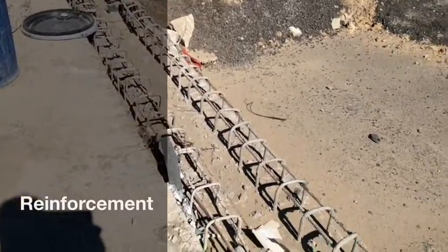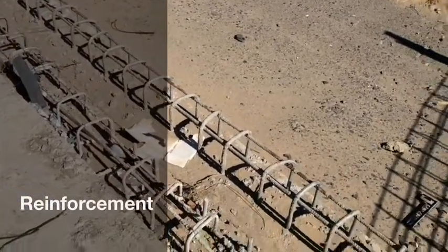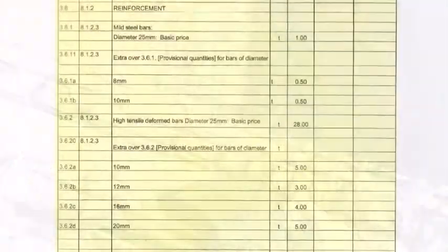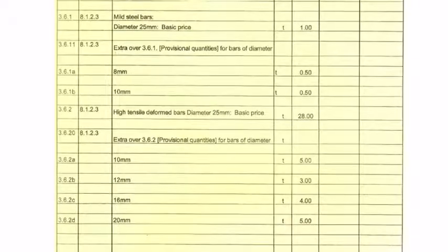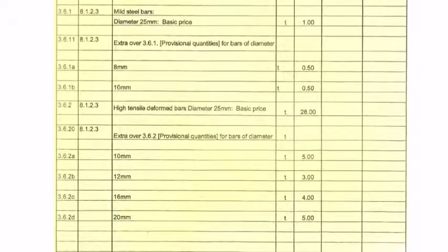For the reinforcement section, this BOQ followed the requirements of the SANS 1200G document for mild steel and high tensile steel. However, welded mesh reinforcement was measured in meter cube instead of meter square as required. We deduced that it was also a typing error.